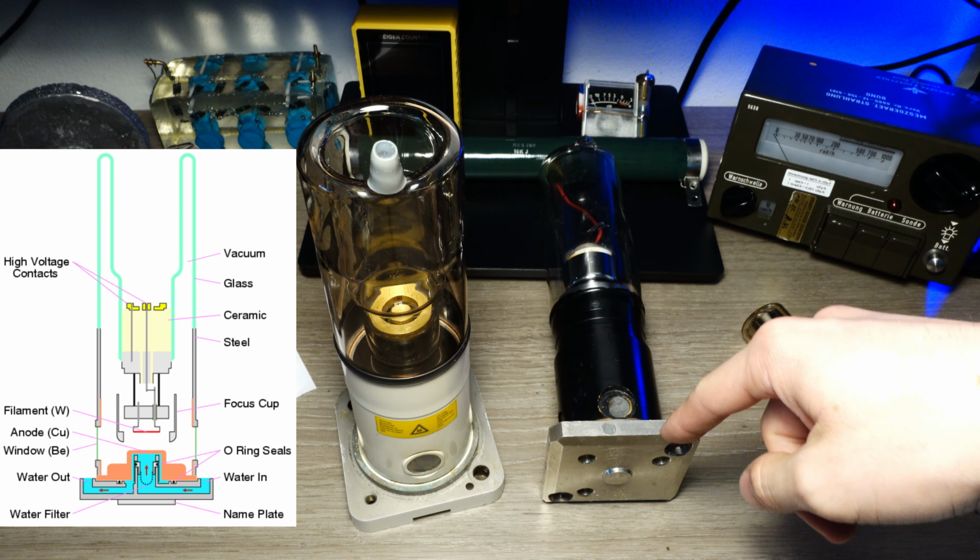These two tubes have also a similar application because they are both used for X-ray diffraction. X-ray diffraction requires a lot of power due to the physical phenomenon happening. Here on the tube you can see in fact the power rating. So this tube worked at a maximum of 60 kilovolt and 2200 watts of power. That is a lot of power that needed to be dissipated.